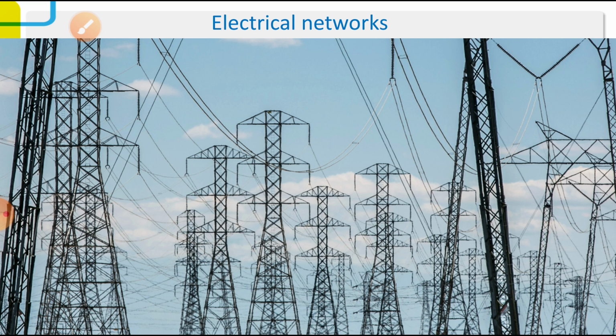So, we have already seen that sometimes it is difficult to solve network problems having more branches with the help of our basic Kirchhoff laws and Ohm's laws, due to a large number of simultaneous equations. These are simplified by star delta transformations. What do you mean by delta and star, or star and delta? Delta connected resistances can be replaced by equivalent star resistances, so that the resistance measured between any two terminals is unchanged. These are all things we have seen in previous classes.